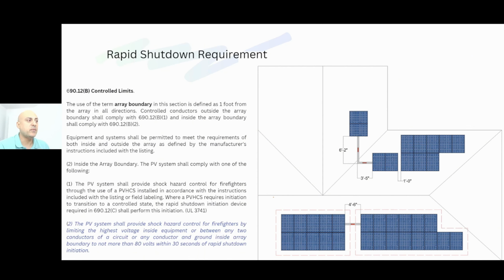or talk to Google about it. So now let's talk about the most common requirements, which is what we explained. Everything that is inside that boundary cannot exceed 80 volts, and anything outside cannot exceed 30 volts. So what's the practical part of it? Let's say that I'm going to have these solar panels, right? These solar panels, the VMP, I'm going to call it 35 volts DC.